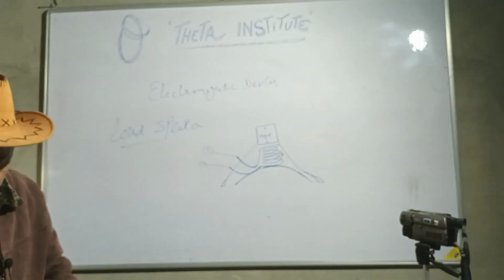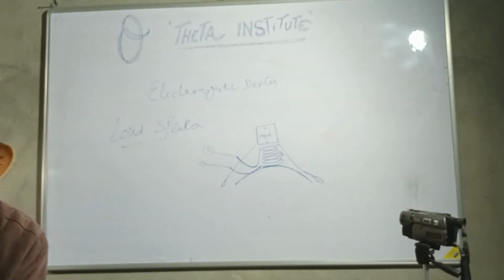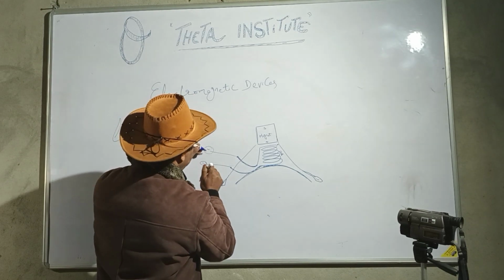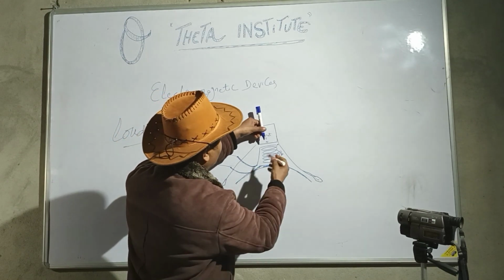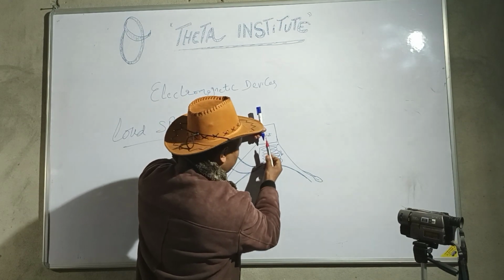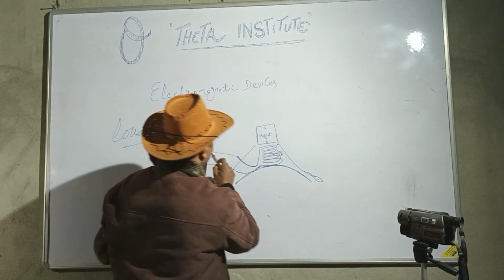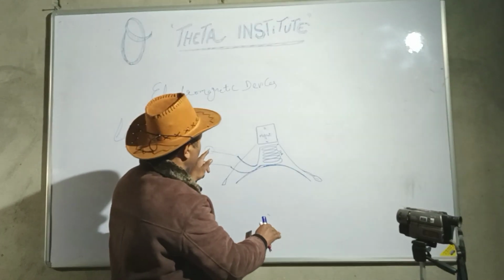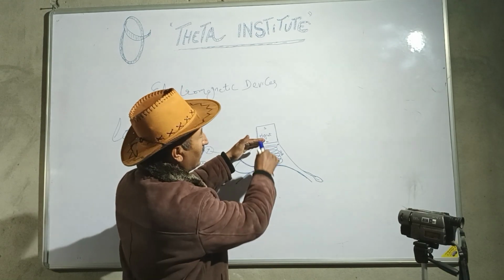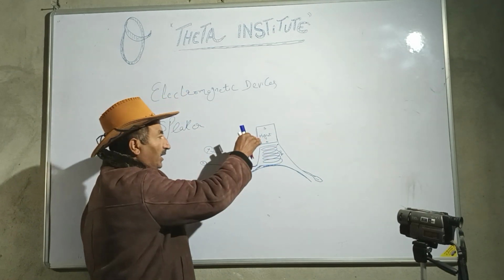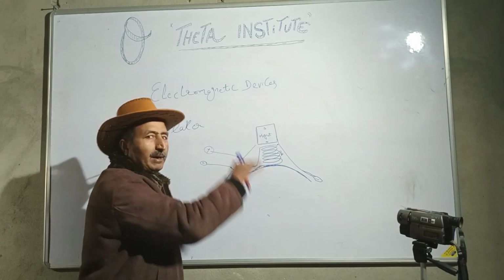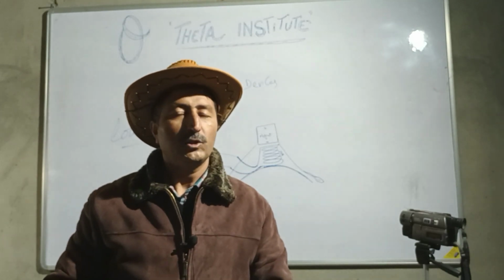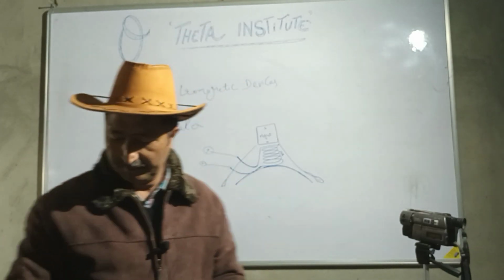If on the other hand this is given a negative signal and this positive, this becomes south and they attract, so the coil goes up. When this becomes positive, it becomes north and the coil goes down. When this becomes negative, it becomes south and the coil goes up. With each up and each down, it pulls the diaphragm up and down, thereby making a sound. That also we will show you practically in later classes.